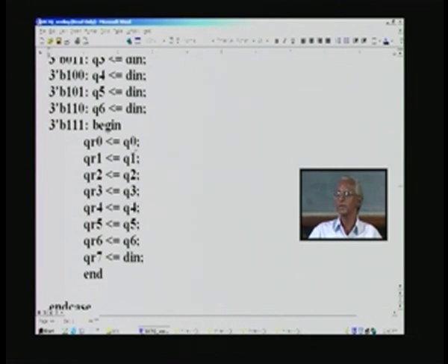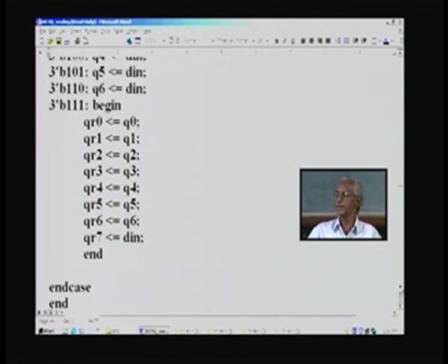That is possible if you write at this stage into another register called QR0. So, with the write at the 8th clock cycle, we transfer all this Q0 through Q6 content into a safe register here, and as well transfer the last thing, which we had not done before, into this. Now, with the arrival of the next clock, this Q0 will be overwritten, but not QR0. QR0 will be overwritten only after all the 8 clock cycles. So, if you examine this, it will be available for the next stage computation to the tune of 8 clock cycles, and this completes the DCT register.